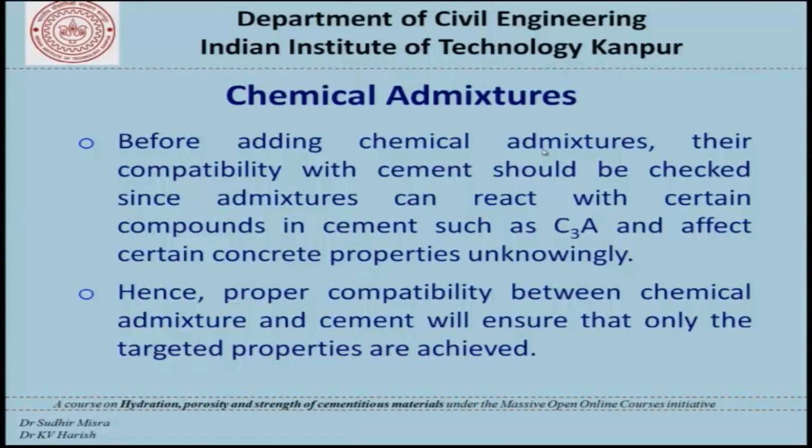Before adding chemical admixture, their compatibility with cement should be checked, since admixtures can react with certain compounds in cement such as C3A and affect certain concrete properties unknowingly. Hence, proper compatibility between chemical admixture and cement will ensure that only the targeted properties are improved or achieved.